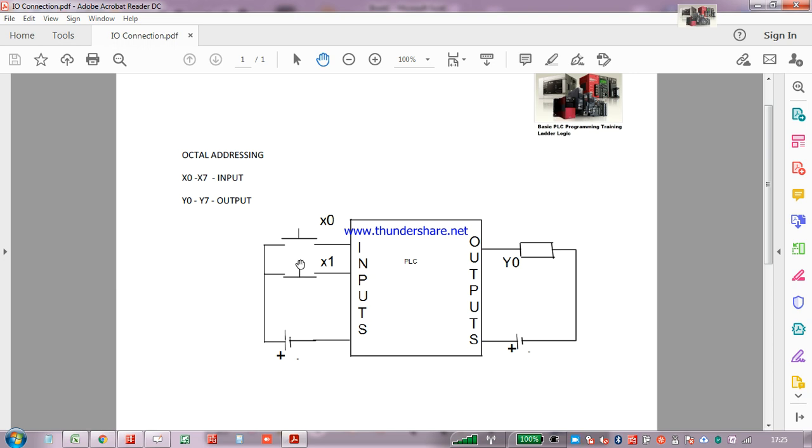Just think of it, if we press and it goes down further, the contact between these two lines is released. So the supply will be cut off, and the input at X1 will turn off. So if we press the button, the PLC will not get the input. You need to consider it like that.